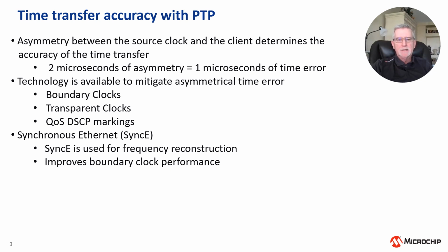Synchronous Ethernet is important when we use on-path support because it does improve the performance of the boundary clocks themselves, even though synchronous Ethernet is not a time transfer technology. It is a frequency reconstruction concept or technology.